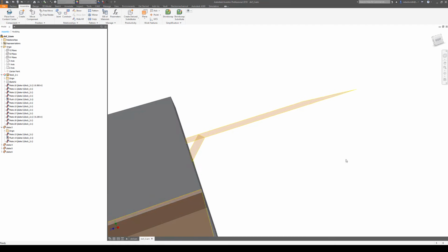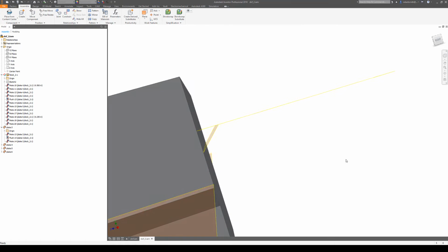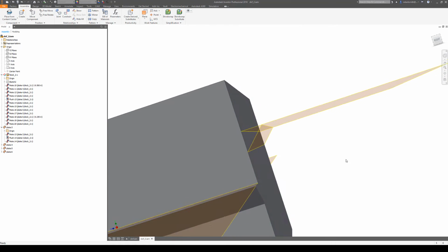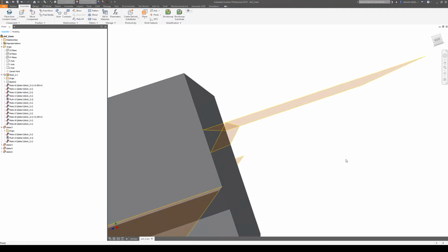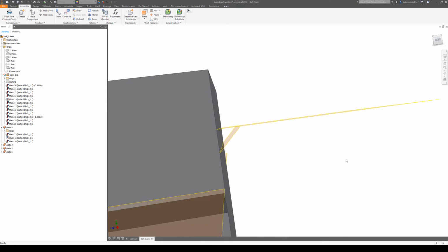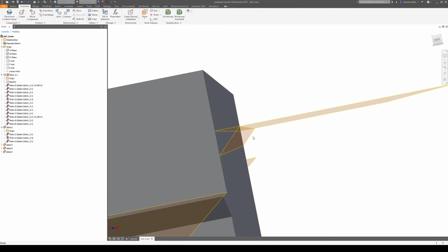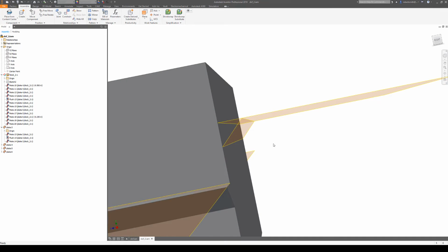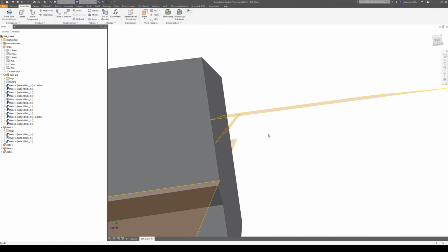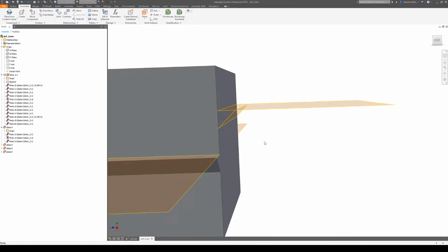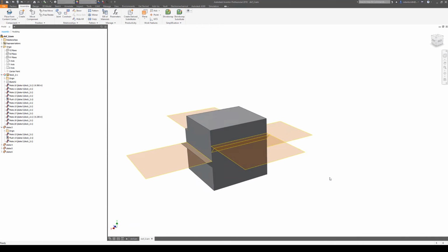I've seen stuff like this where, in this case, I've modeled two plate structures. Both of them would be shell elements, and the bottom one is kind of like a row of gusset plates or something like that. I've seen the same thing done, but with line-based bar or beam elements that just kind of serve as structural supports to prevent that hinge behavior where the two meet.